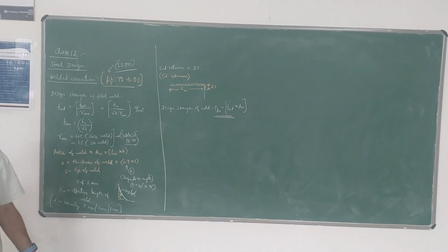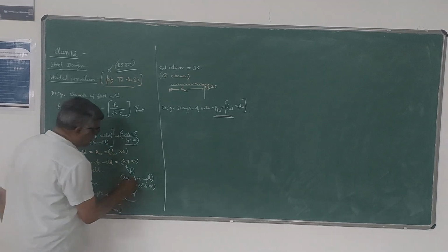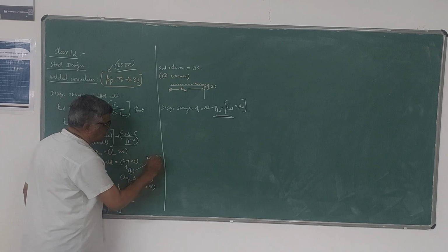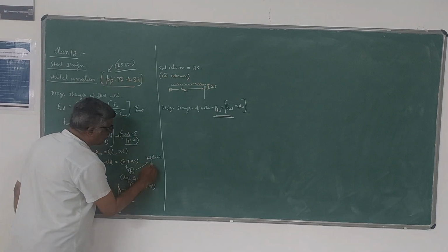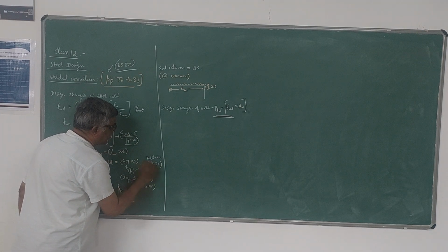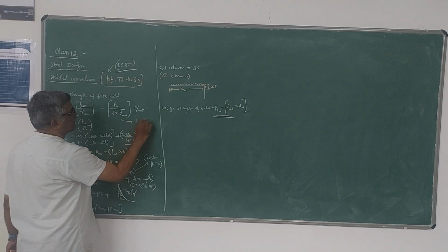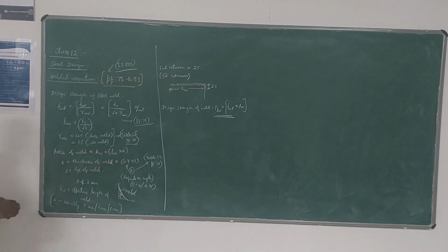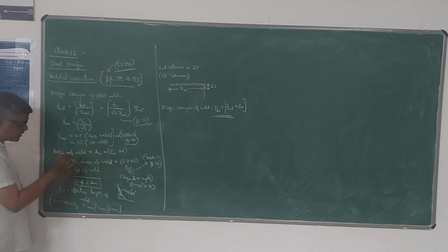Normally in most cases the angle is between 60 and 90. This value is available in Table 22, page 78 of the code, whereas the formula is available on page 79. One important thing here is that the size of the weld should not be less than 3 mm.